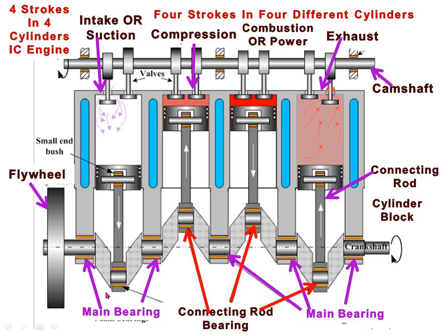You can see here this is the main bearing, which is fitted in the crankcase to rest the crankshaft, and this is the connecting rod bearing, which allows the assembly of the connecting rod and the crankshaft to rotate friction-free.